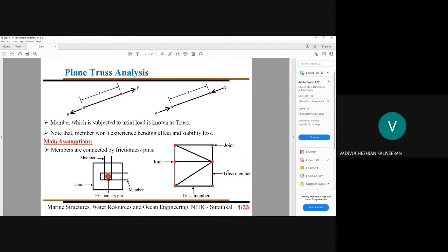So in this particular part, when you think about our truss member, material wastage is not happening. If there is any problem, we are trying to replace only that particular member. The only thing we need is maintenance, proper painting, and we also have to take care of the oxidation effect, using a sacrificial anode sometimes when you use steel or other kinds of material.